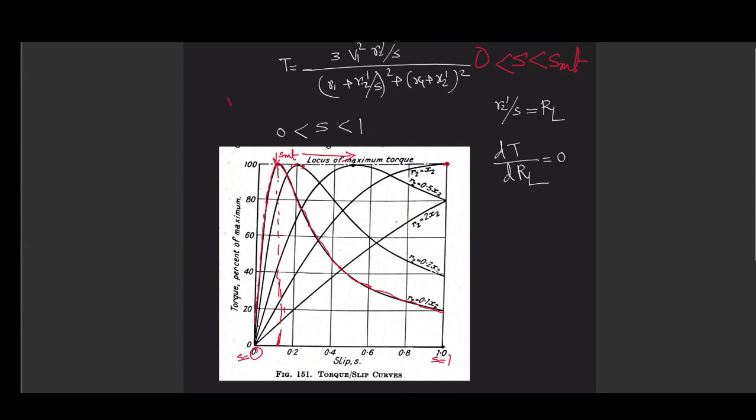The question is very simple. For S is equal to 1, we say that starting torque is proportional to R2 dash. Whether this is a generalized statement, if yes, then it also implies an open circuit condition: if you break the entry and keep your rotor circuit open, then you will have infinite R2 dash and therefore infinite starting torque. But physically your machine will not start.